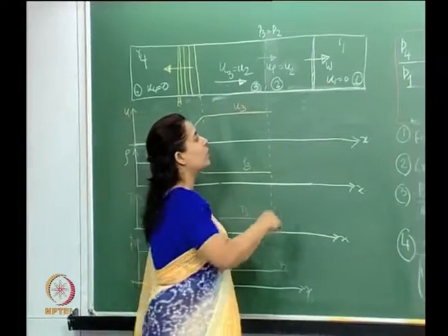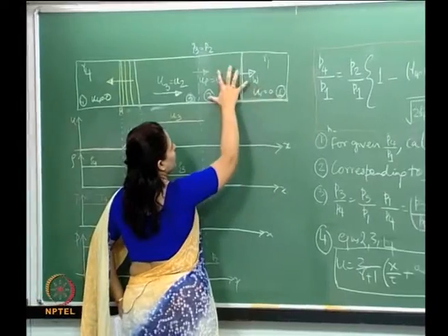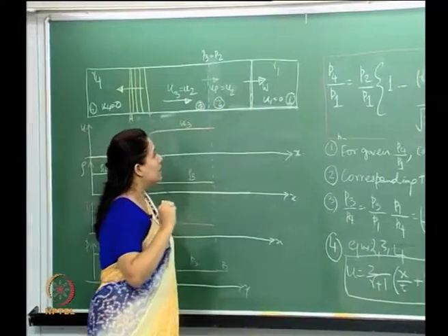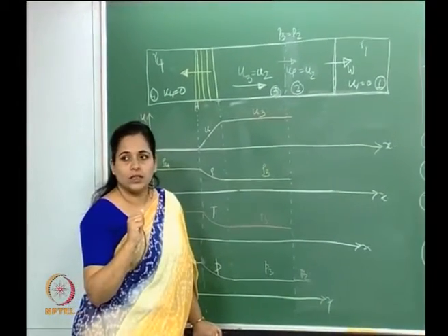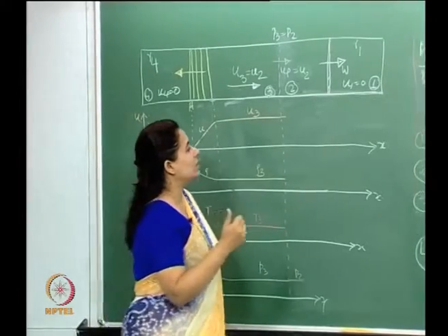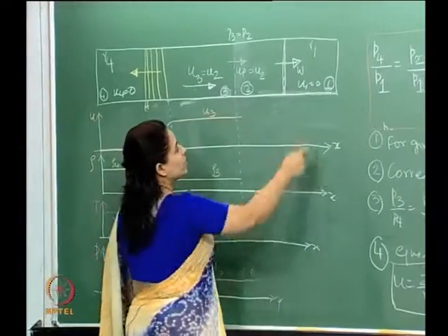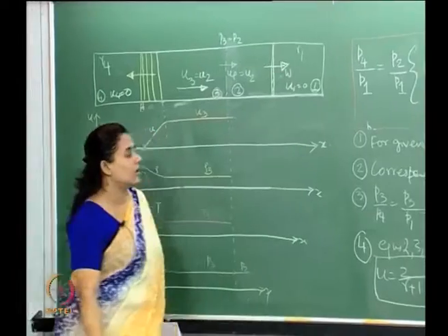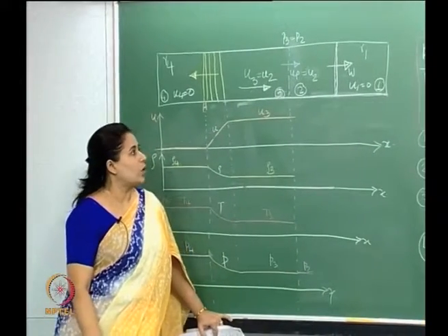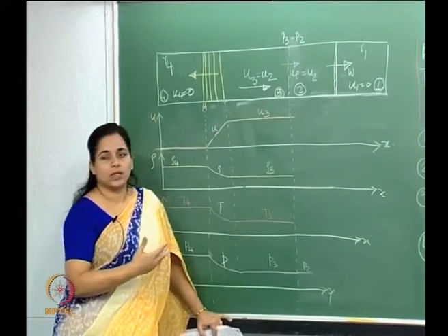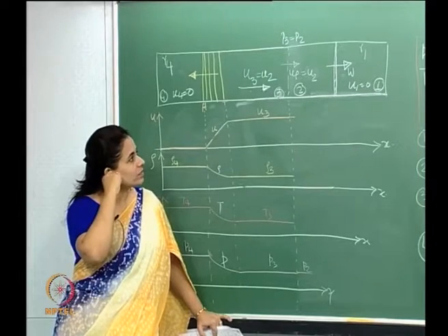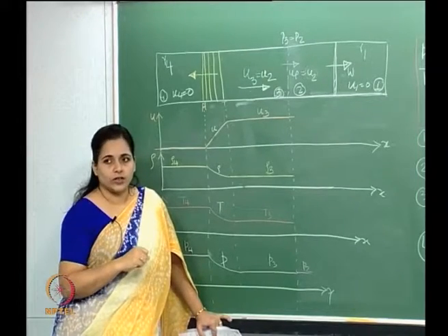For that, all we did was superimpose on these two regions a velocity exactly the same in magnitude but opposite in direction to the velocity of the shock wave, and with that we were able to calculate properties behind and in front of it.